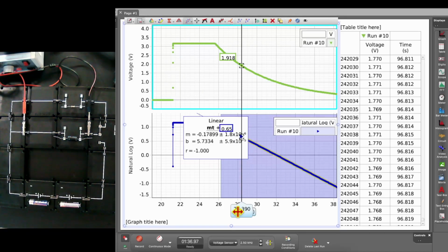You do that for each of the 6 resistor-capacitor circuits. You do 5 decays for each of those. That's the majority of your data taken today. Reminders of the different spots to look at is also depicted on the backboard. In the right-hand side of the board, try to draw out examples of these plots, right? You'll have averages. You'll take the standard deviation, and in this lab, we'll do the standard error as the uncertainty. It's all there, relatively clear. If you have questions, let us know.